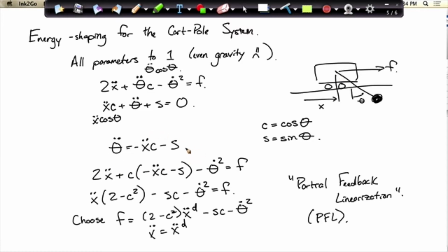By solving this away, I'm just thinking about the contribution of that annoying pendulum hanging off the bottom to the cart, and I'm overriding it, and I can just drive my cart around. Okay? So that's partial feedback linearization. That's a specific idea of partial feedback linearization called co-located partial feedback linearization. Co-located.